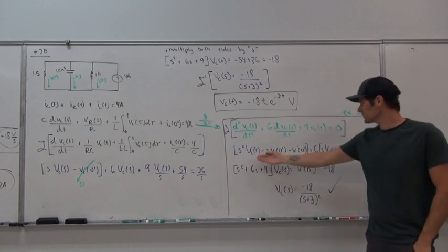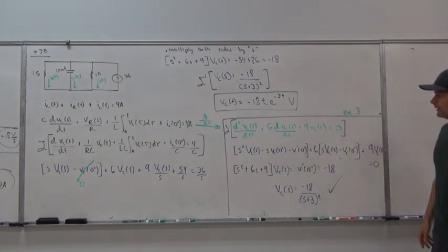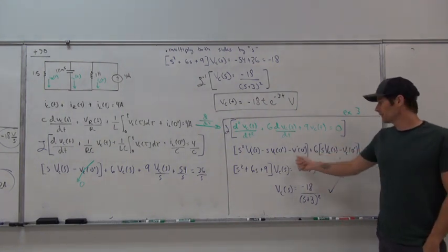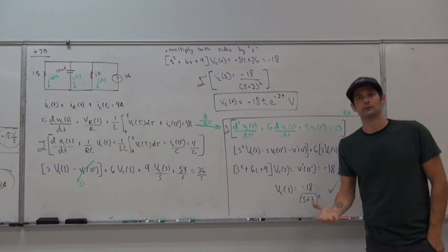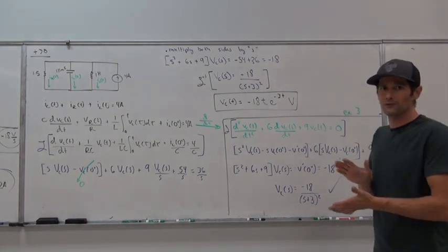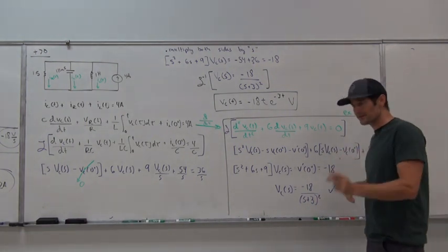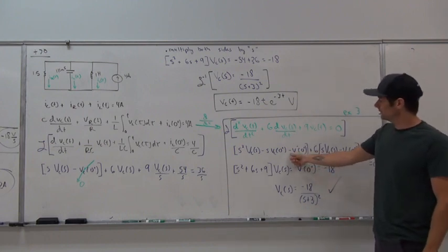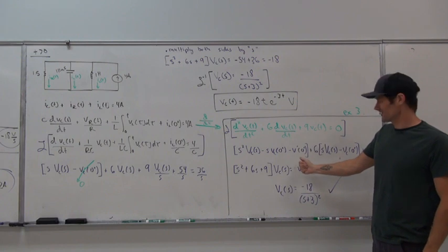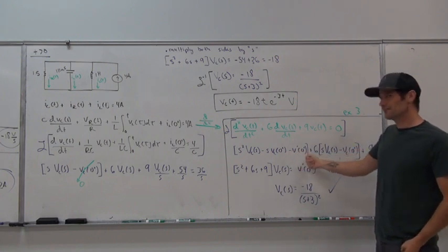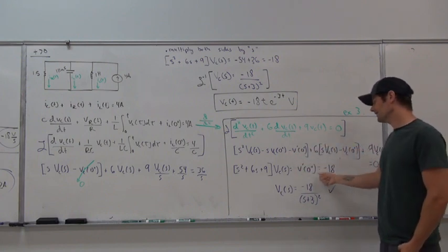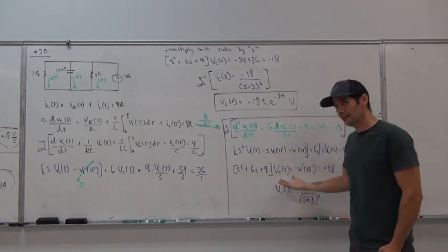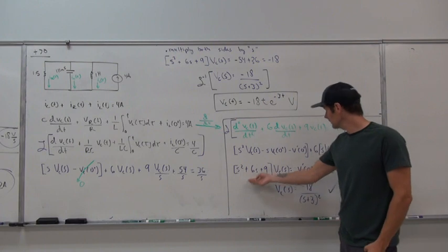We take its Laplace transform and expand it out. Because we have Vc of 0 plus on either side here, both of those are going to be 0, because the initial capacitor voltage was 0 and that held to be the same for t equals 0 plus. But we have a change in the initial condition: here, V prime of 0 plus. We move that over to the other side, just like right here, and combine like variables of Vc of s. We get our characteristic equation.